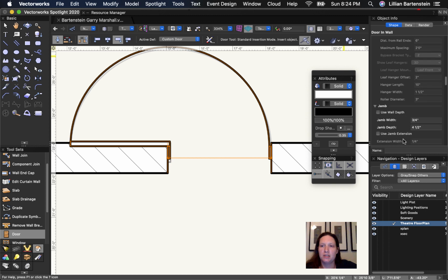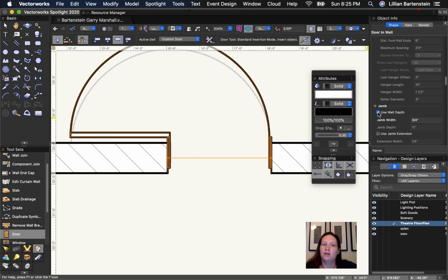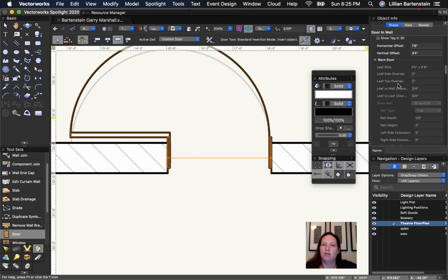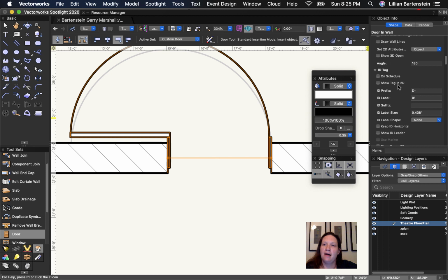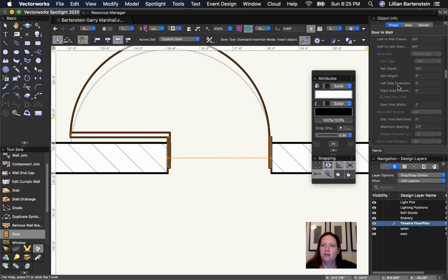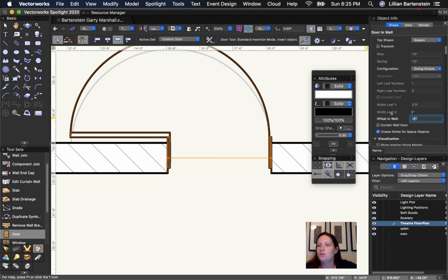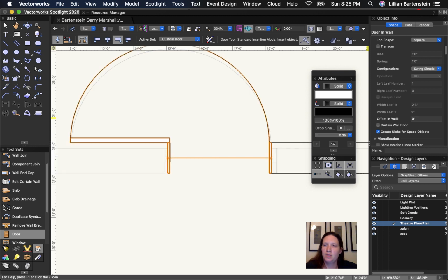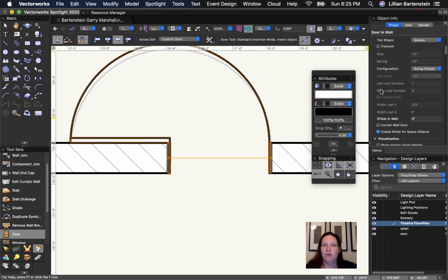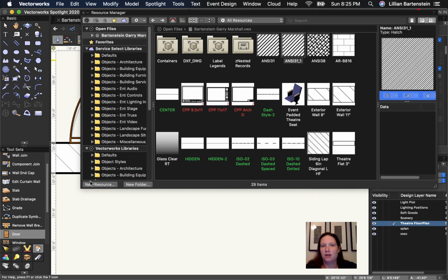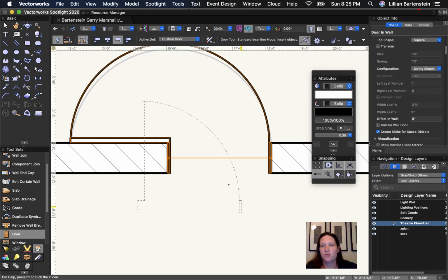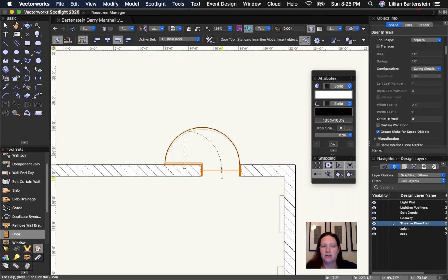So those are some basic deals, right? You have your jamb, use your wall depth for the jamb. So now the door jamb is as wide as the wall, and that will also correct for that offset. So wall back to 0. By adjusting the jamb, now I'm doing a lot better. Okay, so you can kind of tweak those various things until you're happy with the way that your doors look.